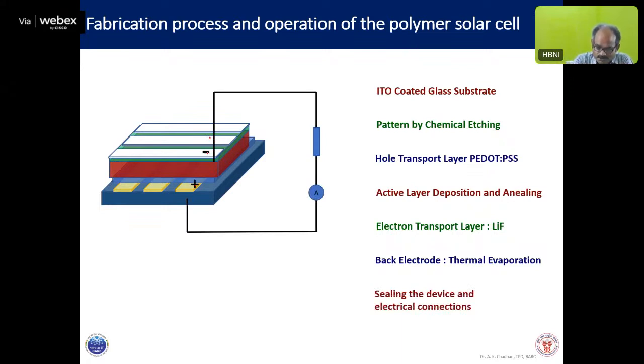Now this portion is connected to this, and this is connected to this one. So suppose now this has become your working solar cell. Now suppose light falls on the active layer, so an exciton is generated. Suppose it reaches the boundary before it recombines. Obviously, the electron-hole pair will be separated, and then these will be collected at the respective electrodes, and after that they will flow through the external circuit through this load, and current will flow, and you will get a working device.